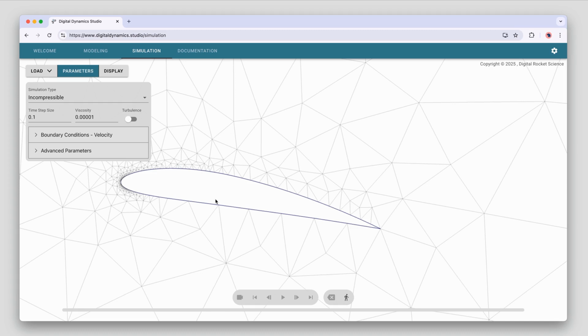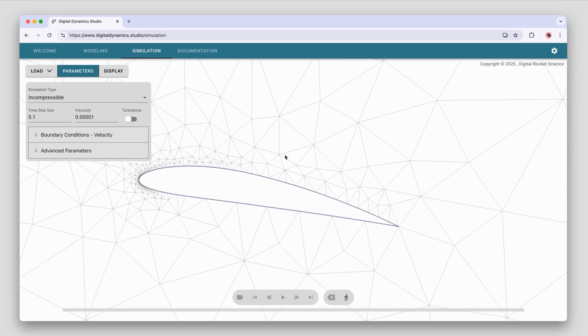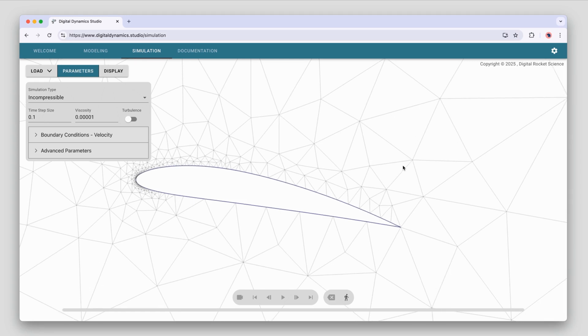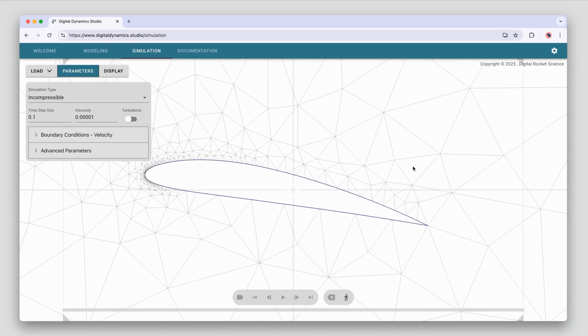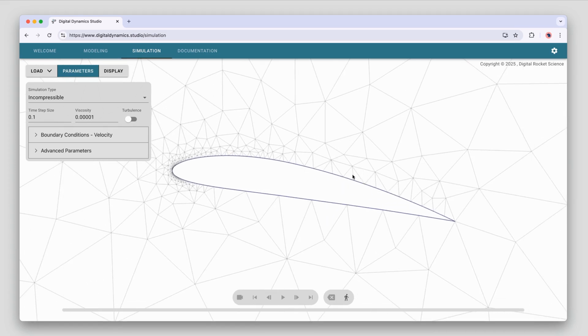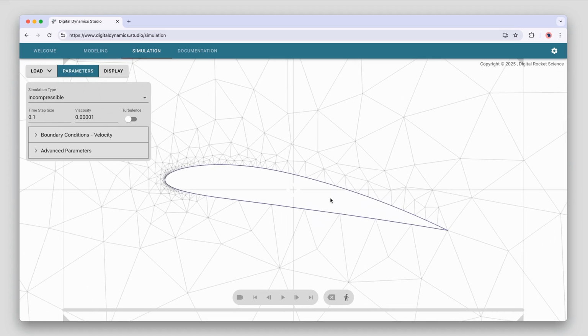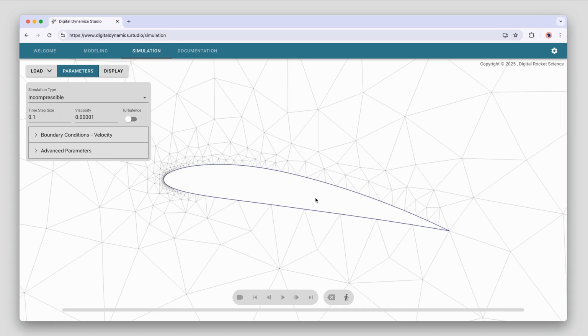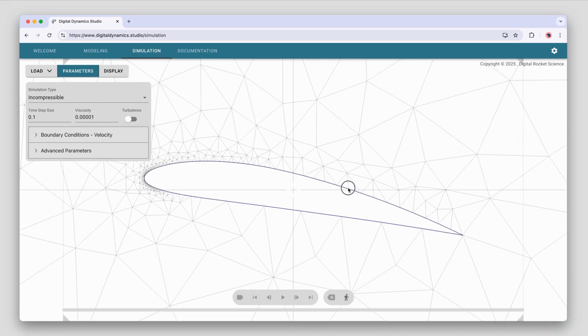And like I said, the features become very small and very microscopic, and meshes like this have a very difficult time. They just can't capture all of those very small, chaotic, turbulent features of the flow at high Reynolds number. So the best we can do is just model them through relationships between their variables, the variables we do know about, and the turbulent energies and what effect they have on the flow.